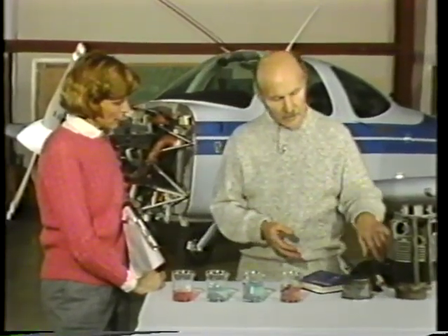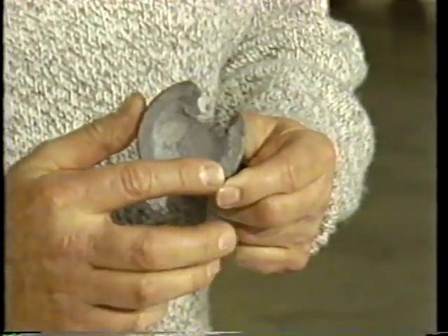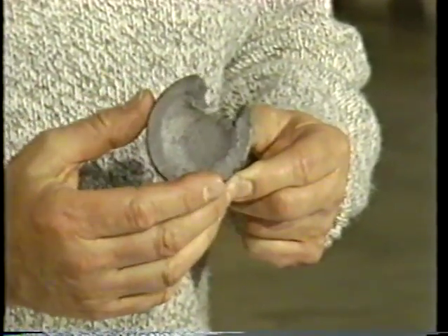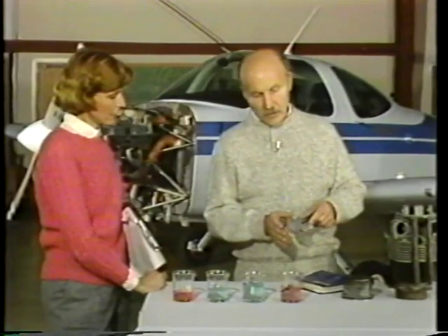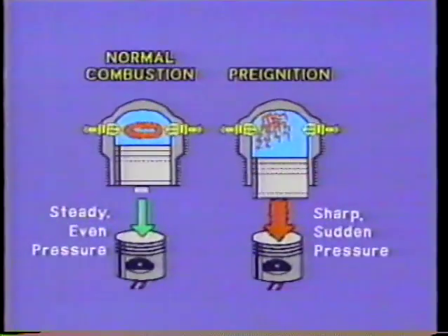Another thing that may occur is damage to your valves, actual burning of the valves due to the excessive heat and pressure that builds up in the cylinders when detonation occurs. There's also another thing that can occur along with this, and that is pre-ignition. Pre-ignition occurs when the fuel-air mixture is ignited by a hot carbon deposit or other source prior to the timed ignition. This causes a rapid rise in cylinder pressure and temperature.